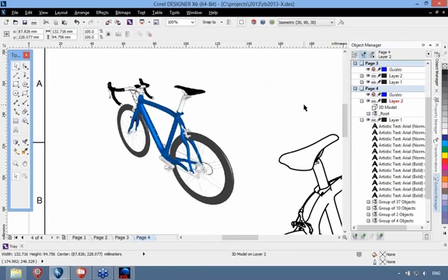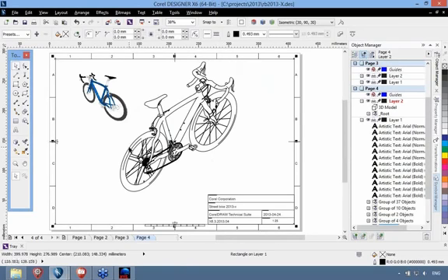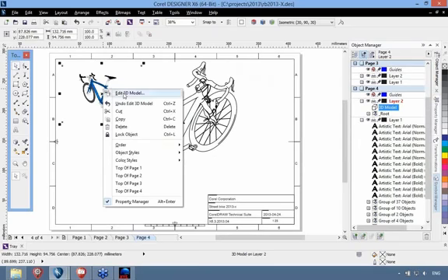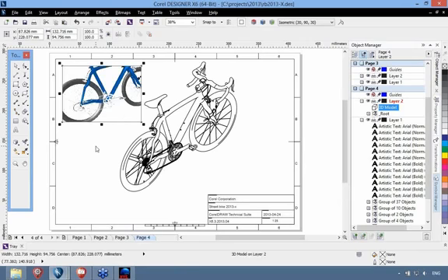For now, let me jump out of it. So you see there's a high resolution preview image of that, and when I move to full screen again, that's part of my file. And if I get to updating that, for example, that 3D file has changed, I have new cameras in there that I can use here, or something has changed in the parts, then I can reload this reference XVL file, and at any time, right mouse click, edit 3D model, or double click into it. I can go back to this editing window and change whatever I want to change to make it look the way I need it. So let me do a bit more obvious change here, and then move out of the editing mode, and there I am with the updated 3D view of my 3D model.